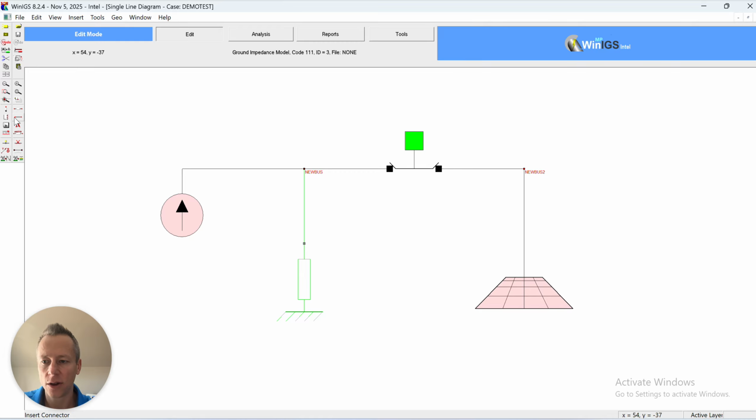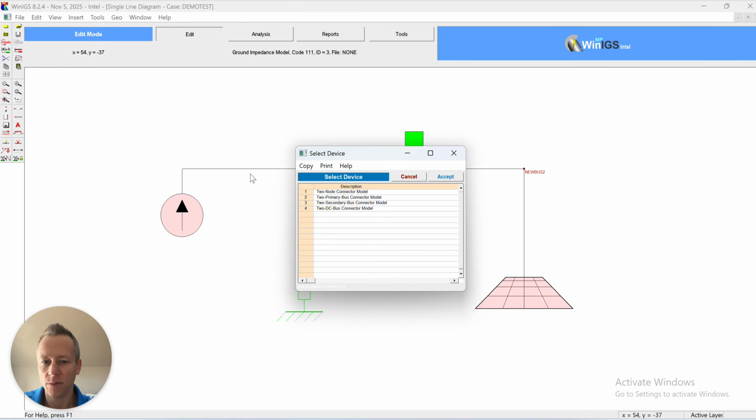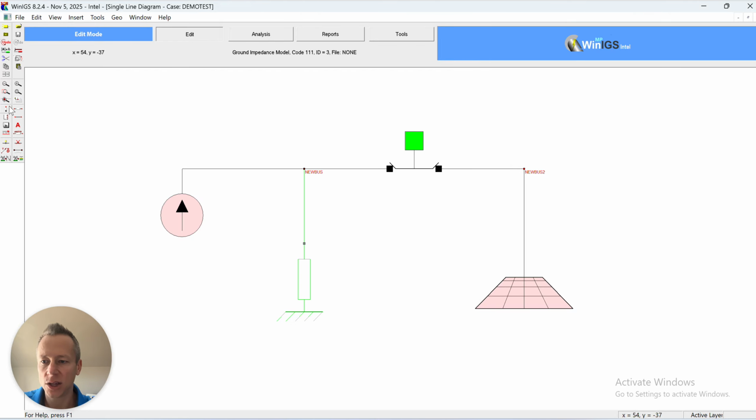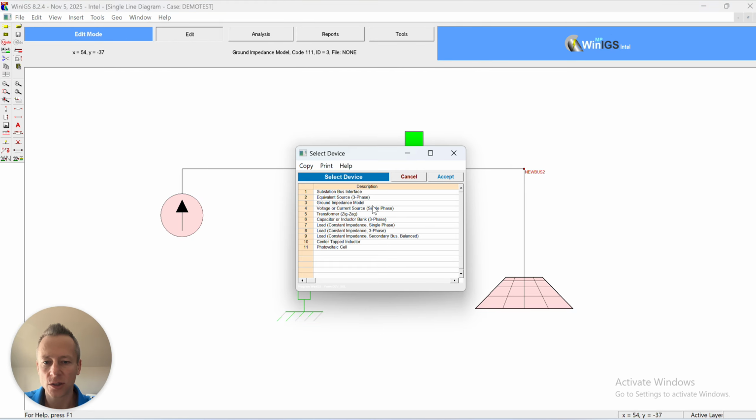We've got the connector from this one, and then the shunt devices was the current source, three-phase source. And again, you can model the transformer. You can model your actual source impedance with transmission lines and distribution lines modeled. It's got a pretty rich interface for modeling those and getting all the accurate parameters that you would want to model.